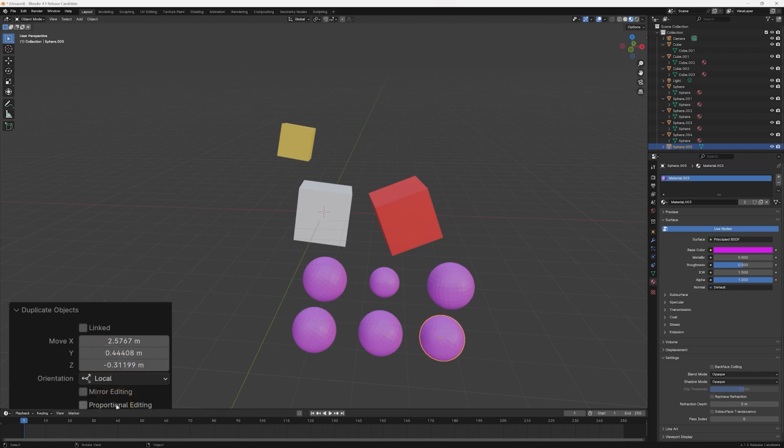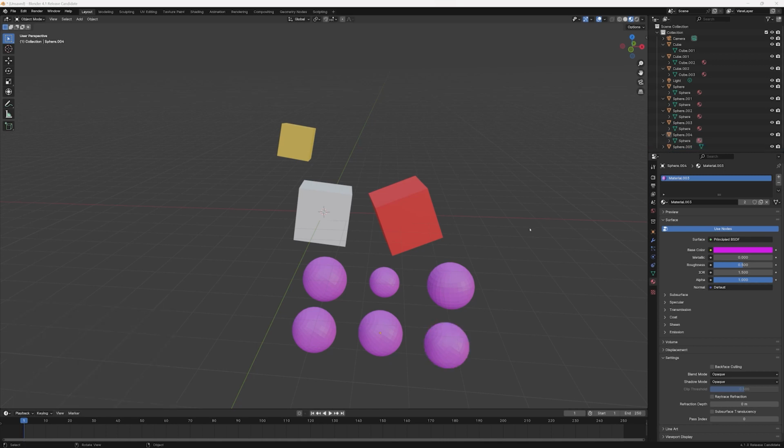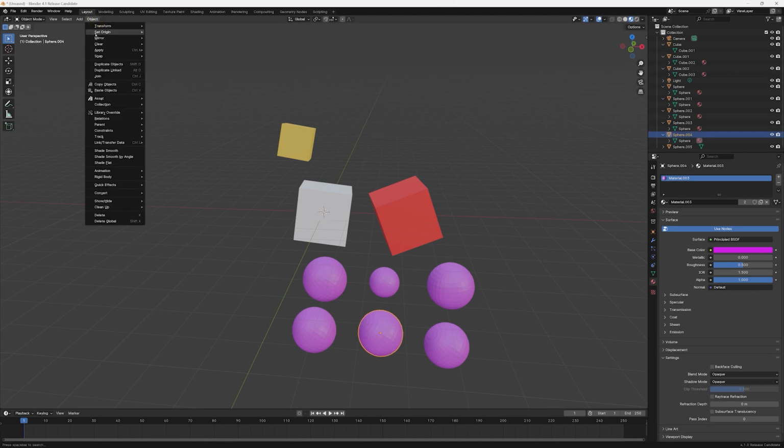After the relevant last op panel has gone, we can still unlink objects that share a data block from the 3D viewport's main menu. After selecting the object to be assigned its own data block, the menu option required is Object Relations, Make Single User, then Object and Data and Materials.